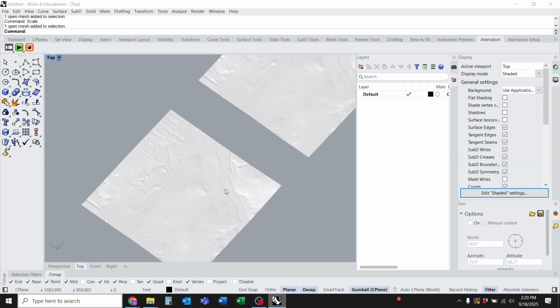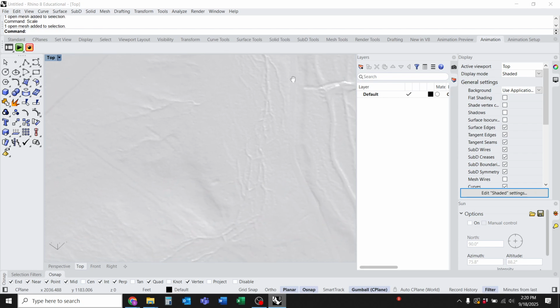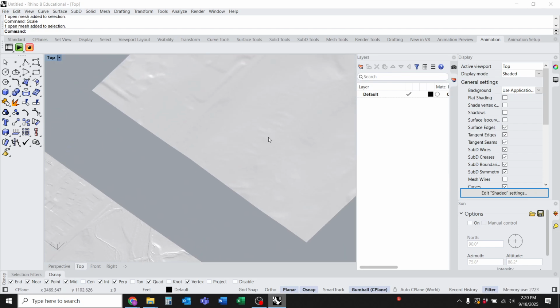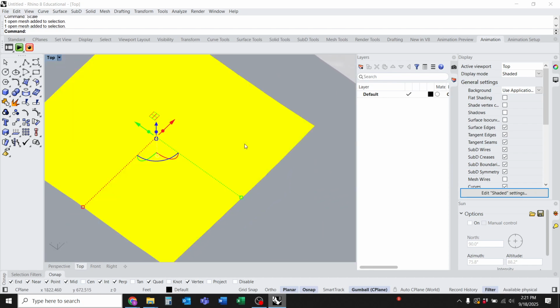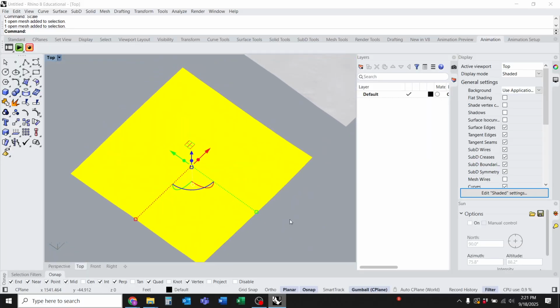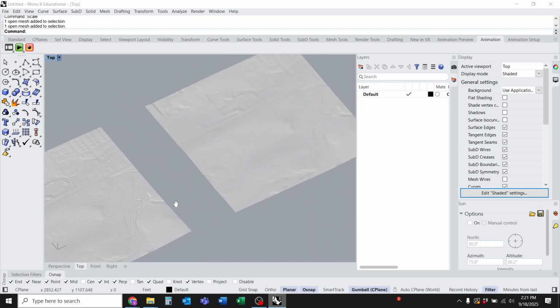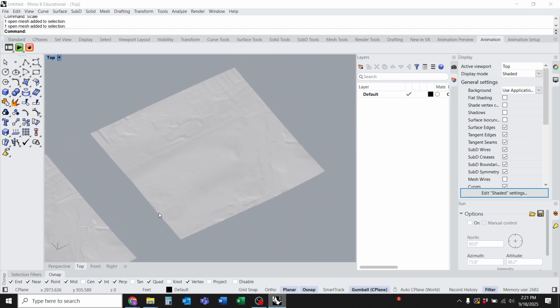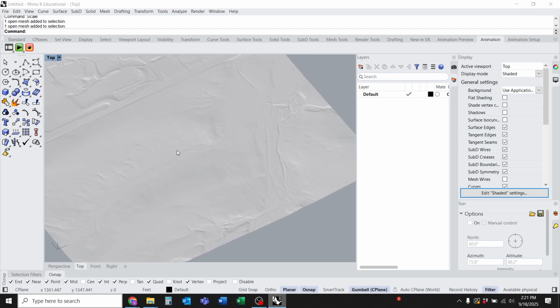But maybe you can tell based on that how much more detail we have in the surface where I set that resolution to 2 versus 10. Of course, we also have a much more dense mesh. So if you were going to stitch together, say, 15 of these squares for that larger scale, you would do a lower resolution, versus if you wanted a more zoomed in approach, you'd do a higher resolution or a higher sample rate.